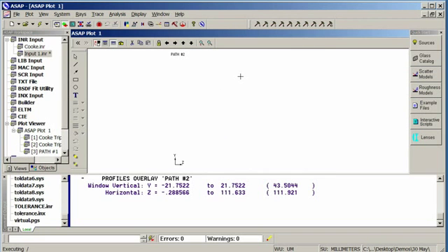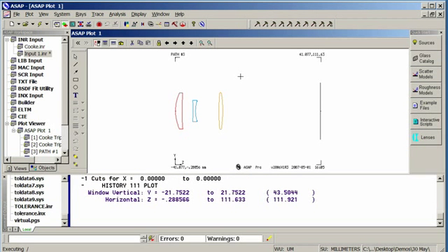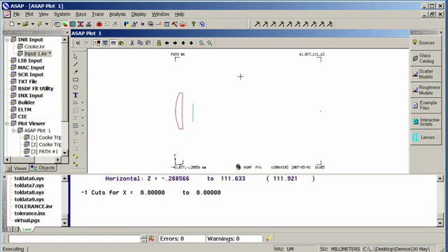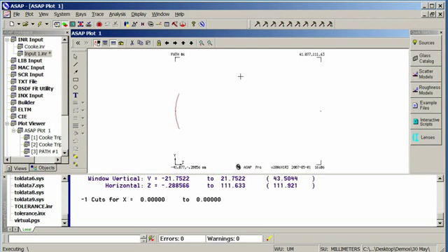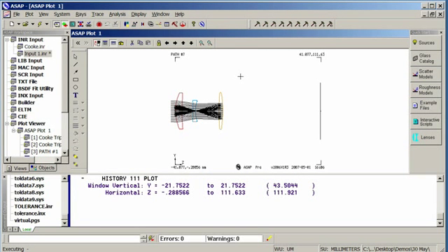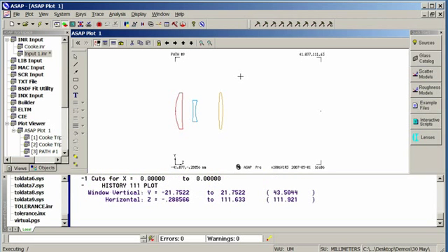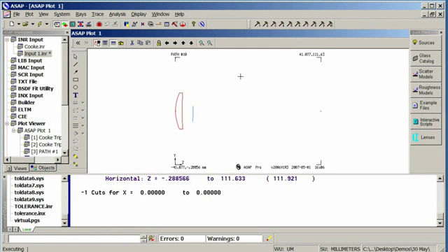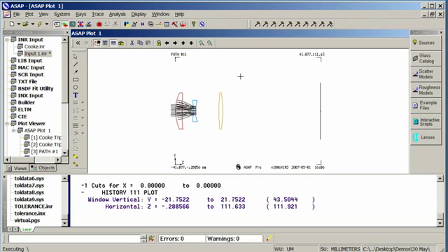And there's my basic ray path, my imaging ray path, and now here are the other paths that had significant energy. And in terms of decreasing energy, it shouldn't be surprising to see that it goes in the order of Fresnel reflections off each surface, because obviously as we go from surface to surface, energy was lost on the previous surfaces by 2 Fresnel reflections, so as we go through, each subsequent set of rays will have slightly less energy. We're also going to get some second-order effects, some scattering effects. We could have scattering effects, although we didn't include that in this particular design.